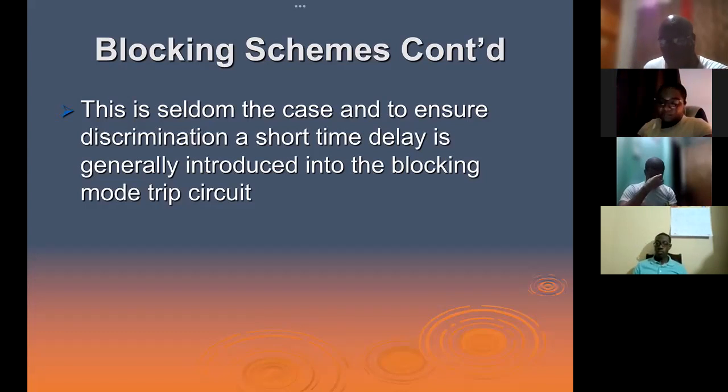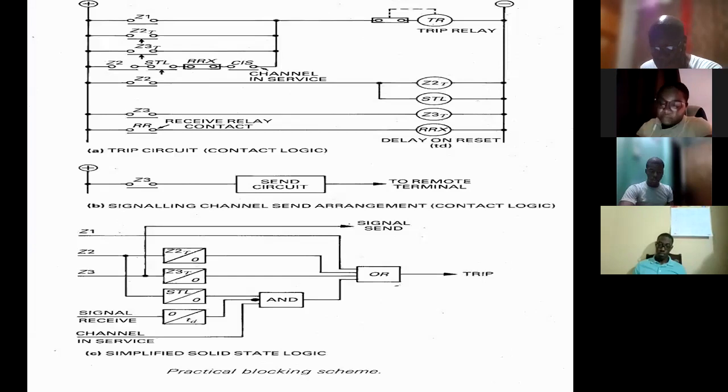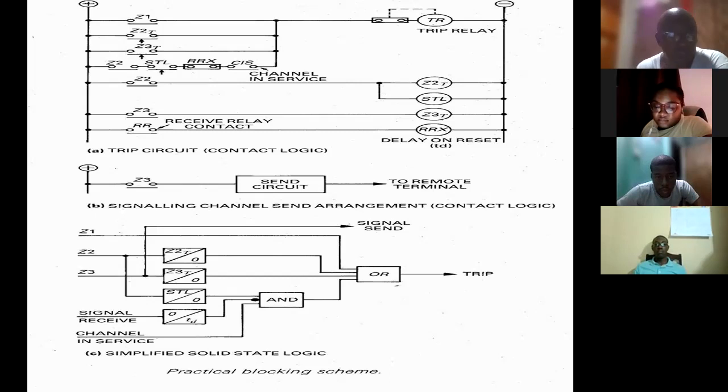So finally tonight, we just look at what we refer to as a practical blocking scheme. All right? So practical blocking scheme, as I said, we just put all of what I mentioned in series to ensure that we check each box before operation occurs. All right? Because the blocking scheme, in terms of speed, is the fastest of all that we have looked at. In terms, fastest and most secure.